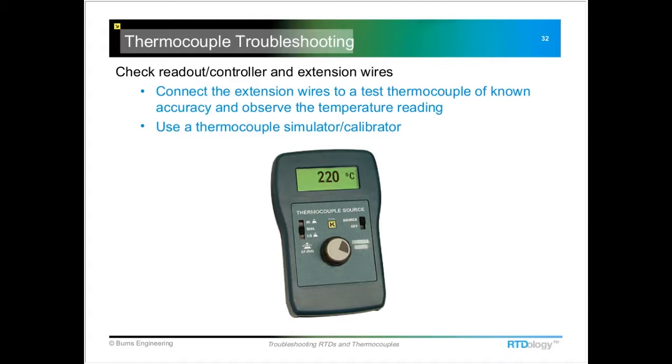No, there's just a given number of thermocouple types. There's the base metal types, which is type J, K, T, E, and then there's a type N also. Yeah, any of those can be used for either surface temperature or air temperature. There are some differences in accuracy between them. Like a type T has the capability of being the most accurate.